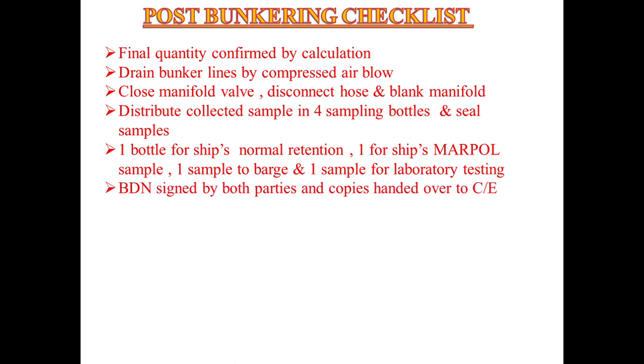Now, then we talk about the BDN signed by both parties and copies handed over to the chief engineer. So the bunker delivery note is signed by both the parties and copies are handed over to the chief engineer. Then we have an entry about the bunker delivery in the oil record book. We are supposed to make an oil record entry of this in the oil record book. I have already covered a video on what entries are to be made in oil record book part 1 and part 2, that is machinery space and cargo space. You can watch that video.